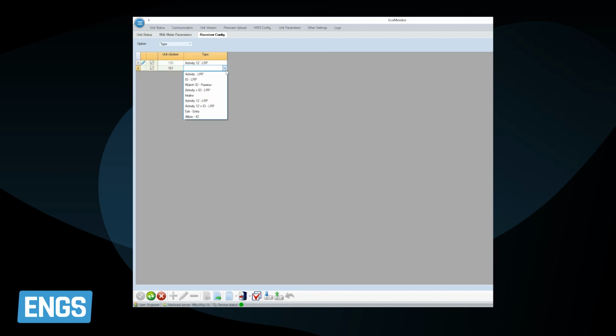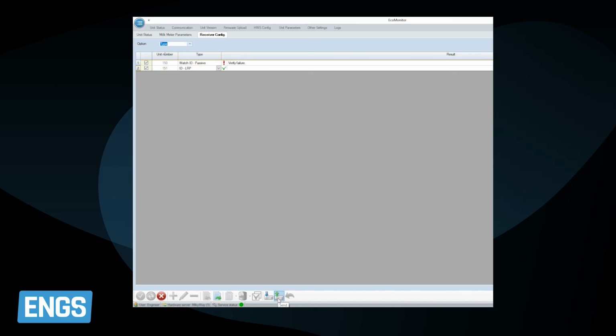After the units are configured, click on the Send button to send the parameters to the units. When the parameters have been sent successfully, the blue pencil will disappear and a green check will appear as a result. Continue this procedure for each of the components you have configured in the system. The configuration is now completed. We recommend you go back and check all of the settings once more. Then, when you have finished, log out as engineer.